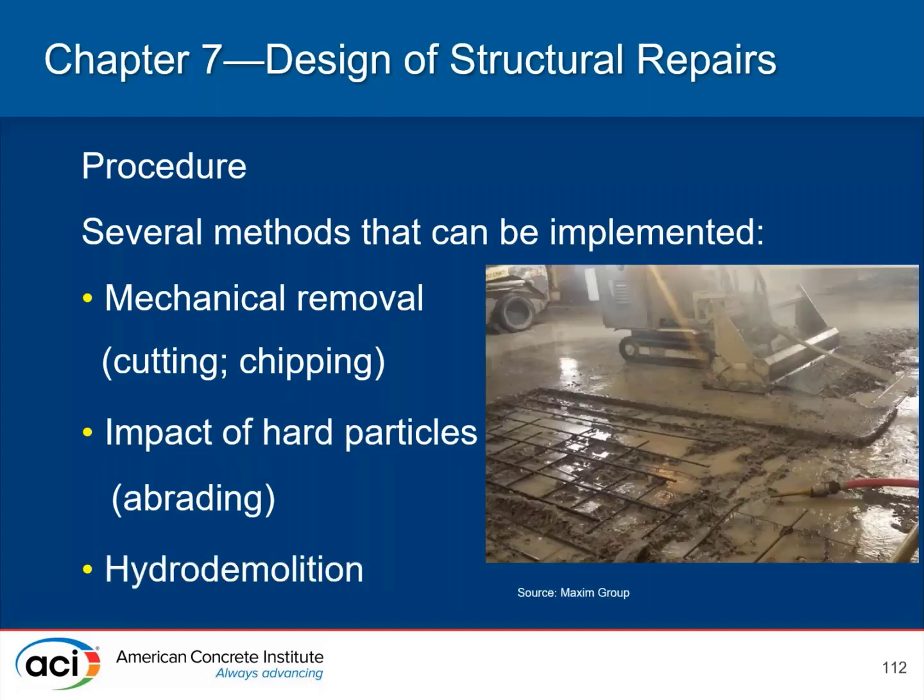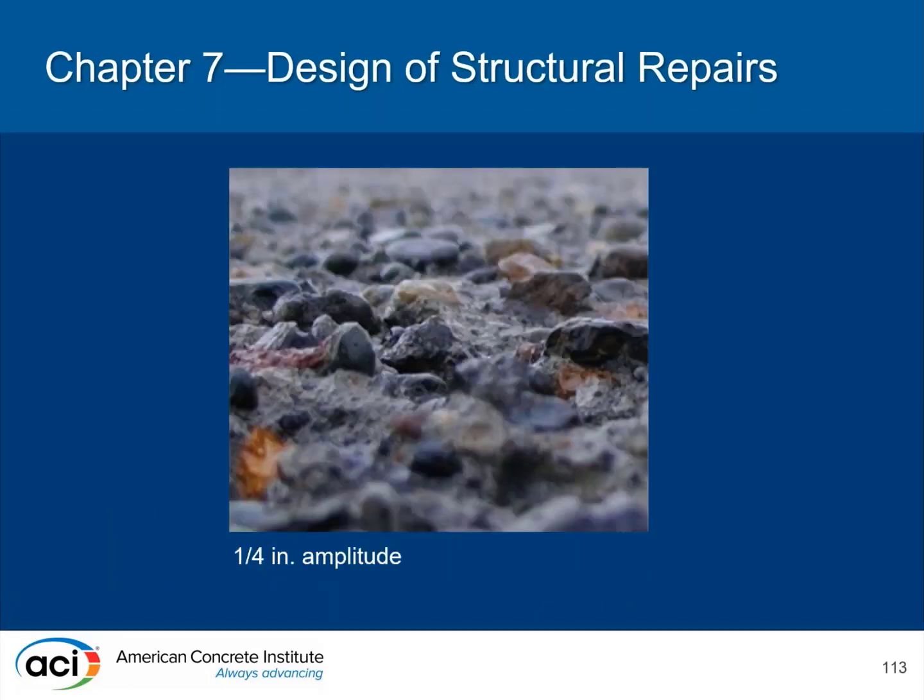Hydro demolition, which is shown here, can be used as an approach to remove unsound and deteriorated concrete as well as sound concrete, and generally speaking, it can create a profile with significant amplitudes, and it also has a low propensity for bruising and microfractures. Here is a picture of a hydro demolished surface. You can see that it has a very good amplitude.